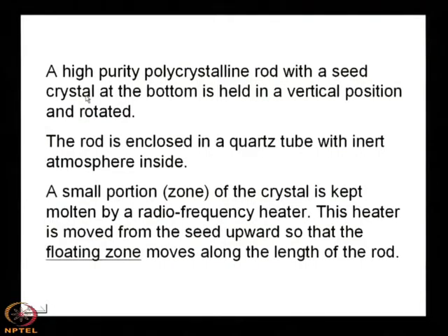Now, what is the necessity of a seed crystal? Why do we use a seed crystal for the growth of any crystal? Why is it required at all? Yes, basically we want a particular orientation of the crystal: 100, 111, 101, any particular orientation. So, there is a melt and it crystallizes by solidification, and during solidification if you introduce a seed crystal, the crystallization takes place in a better way with a particular orientation.